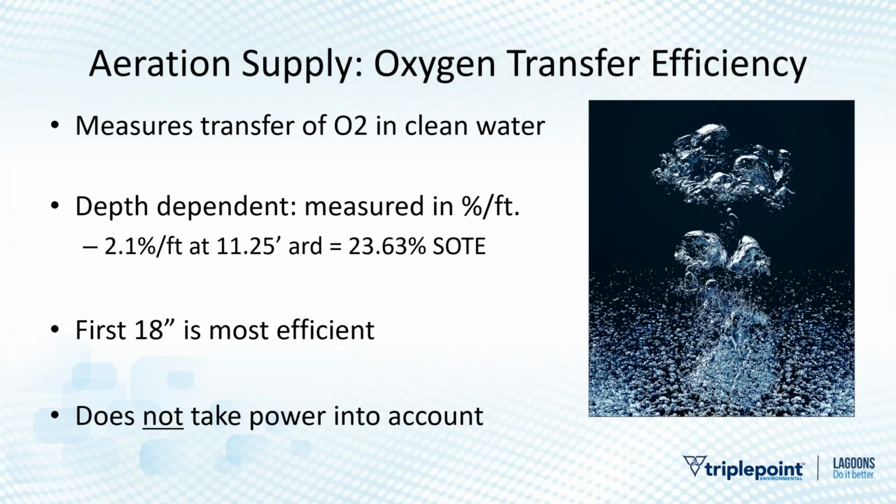But from a diffused aeration standpoint, we have oxygen transfer efficiency. And this is a measure of how fast or how well we can transfer oxygen to clean water with a particular device. And in general, this is measured in % per foot of submergence.